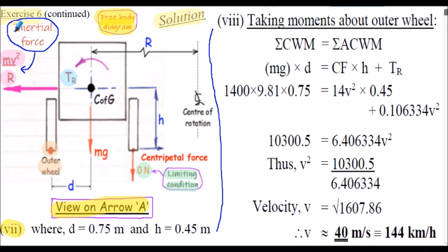Note that mv squared upon r, the centrifugal force, is termed an inertial force. We considered such forces in our previous presentation related to D'Alembert's principle. And as we stated earlier in the presentation, Tr is termed the inertia couple. So the inertial centrifugal force and the inertial couple are effectively applied to the free body diagram, and they basically bring what's called a dynamic situation into a static situation.